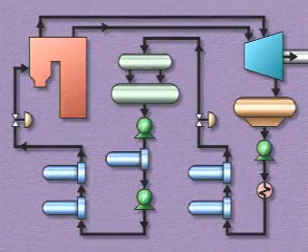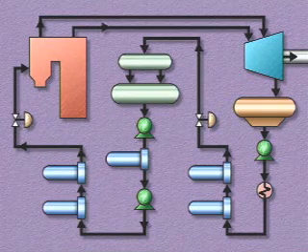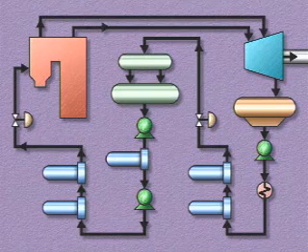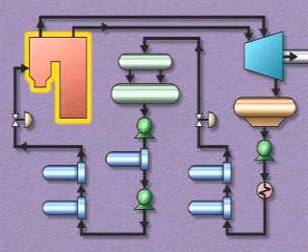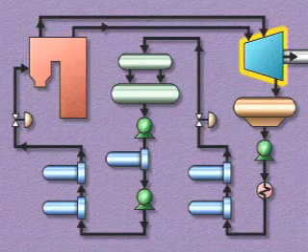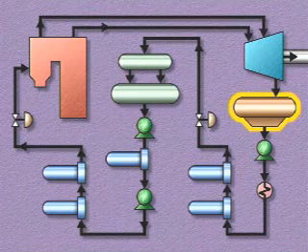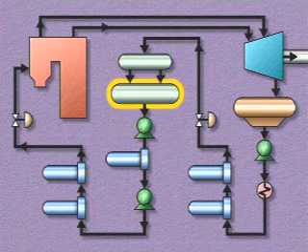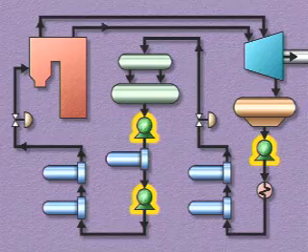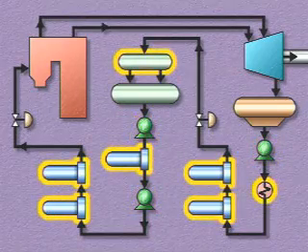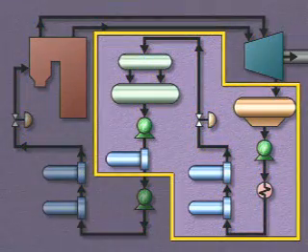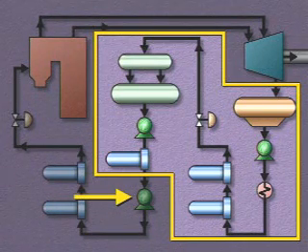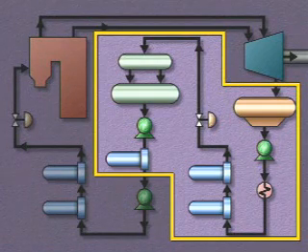This simplified illustration shows the arrangement or layout of some of the major components of a typical condensate and feedwater system and a main steam system. Included are a boiler, a turbine, a main condenser, a feedwater storage tank, and various pumps, heaters, valves, and piping. The area between the main condenser and the suction of this pump, the boiler feed pump, is the condensate side of the system. We'll look at it first.